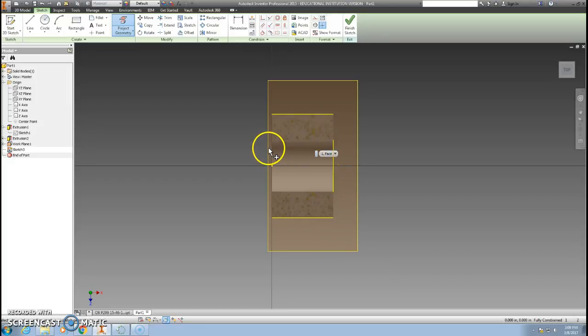So I've already lined up the two cylinders on the left side. They're spaced 2 3/4 apart. Looking from my right side, I need 1/8 inch of space from this edge to the elliptical shape. So I projected the geometry of that line right there so I can measure that. First I'm going to offset this line 1/8 inch, and then offset that another 1/2 inch because that is the thickness of my ellipse. So I've got the length of my ellipse, and then the width of it.